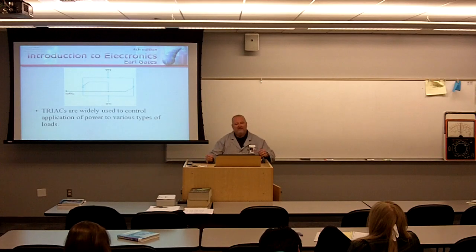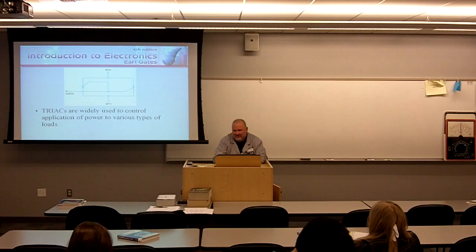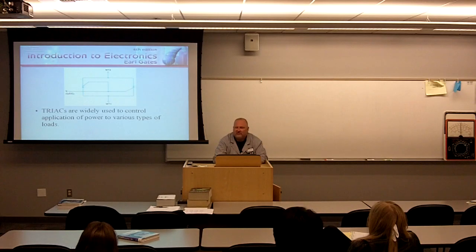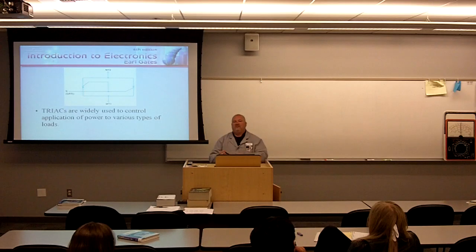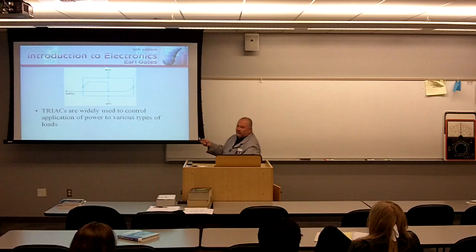And it's a new component, so guess what? We've got some new lead names. But again, they did this really to make it easier for us. If we have an anode and cathode, as soon as I say anode and cathode, you assume polarity, right? Does one of these triacs have polarity associated with it? No, it'll conduct positive or negative. So what they've done now is they've called it MT1, main terminal 1, main terminal 2, and a gate.